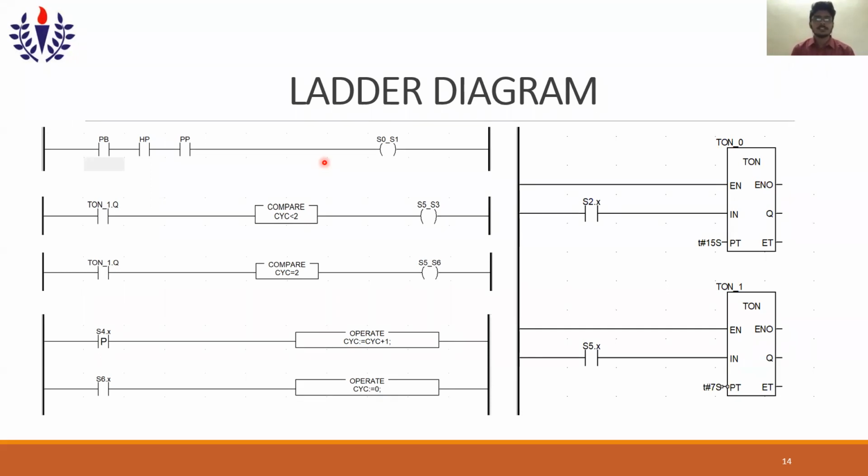When we go to the 5th step, we have a choice. If the circuit is complete, if we are satisfied, we go to the 6th step. If not, we go back again. The top timer is for compare cycle 1, that is to go back to the intermediate position, while the one below is where we confirm that yes, the condition has been reached.